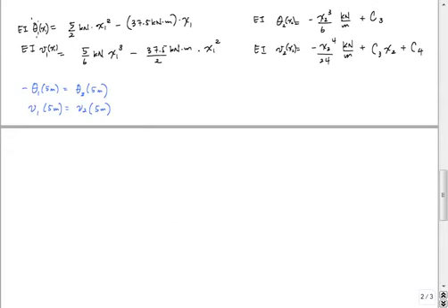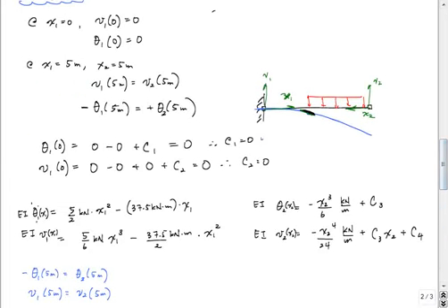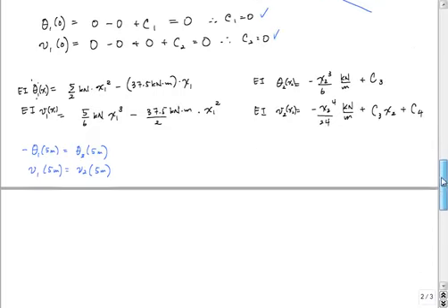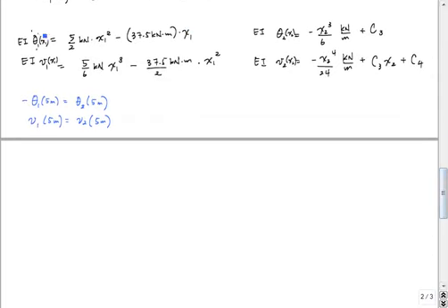All right, so we're back for part 3 in this beam deflection calculation using the double integration method. So far, using a couple other boundary conditions, we found that C1 and C2 were 0, using these two boundary conditions: that the displacement at the fixed support is 0 and the slope at the fixed support is 0. I took the liberty of rewriting the equations that we have here. This is the slope function for segment 1, and the displacement function, or the equation of the elastic curve, for x1. These are my two equations with the constants already introduced.